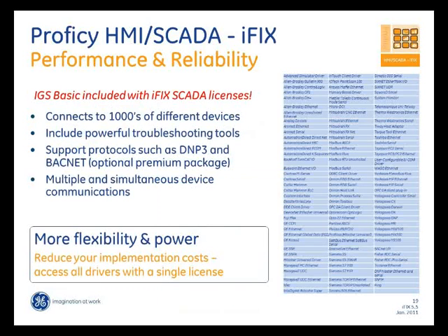The other thing that is part of iFIX 5.5 now is the IGS basic driver is now part of every iFIX SCADA license. Apart from the iFIX 75 tag count package, which includes an IGS 75 points, all of the iFIX SCADA packages will include IGS basic. And what that means is the IGS basic includes about 70 plus basic protocols that come with it.